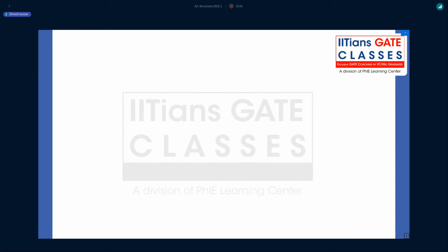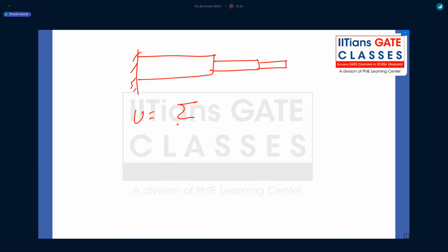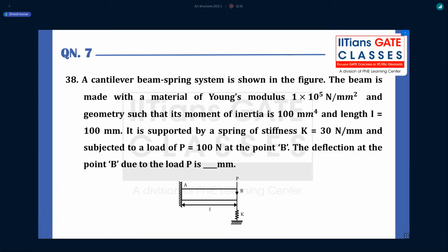Now suppose you have a stepped bar or rod like this. In that case, how is the strain energy? It will be the summation, i equal to 1 to n, of Ni square Li upon 2 Ai Ei. So all these cases you should remember from the GATE perspective. Okay, so let's move to the next question.